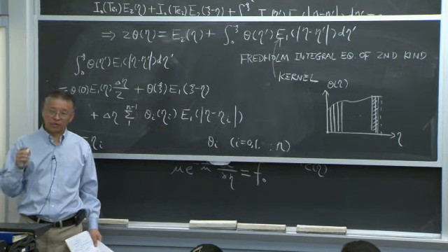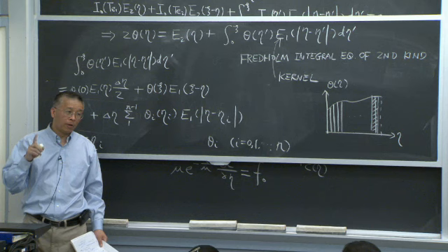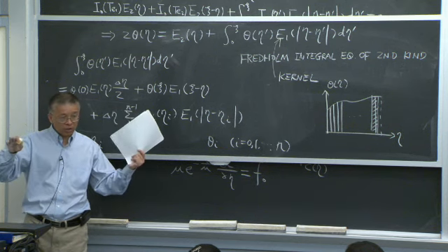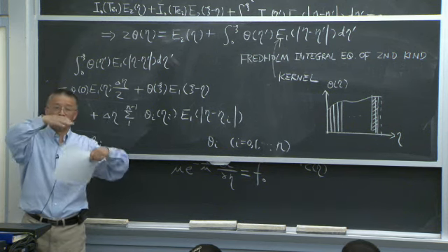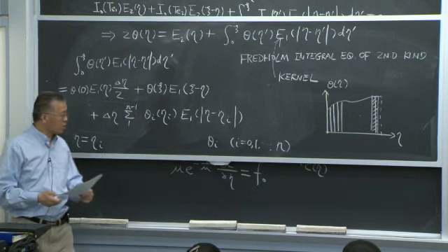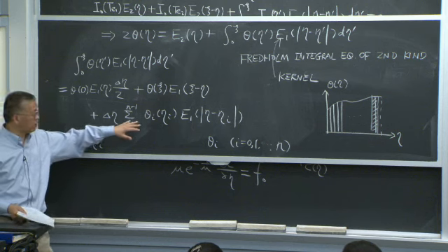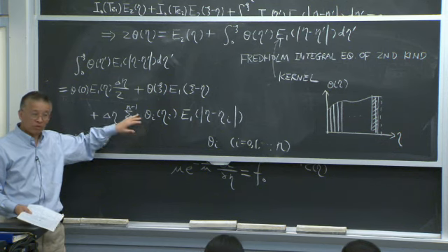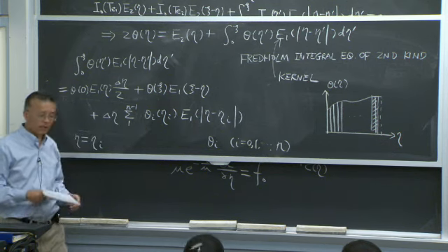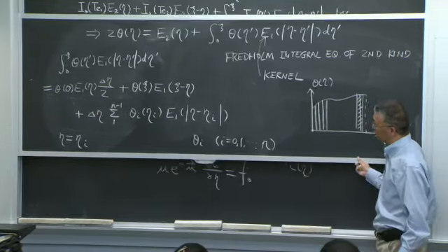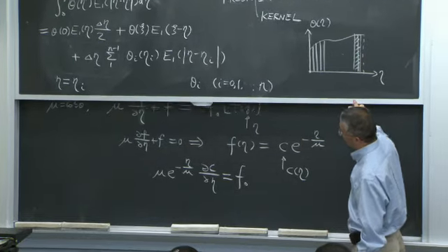And this matrix is different from when you solve the Fourier heat conduction equation or the Navier-Stokes equation. In that case, your matrix is mostly 0, except the diagonal and the two lines adjacent to the diagonal. This matrix is typically a full matrix because every term is non-zero. Okay, so you need to invert that matrix to find the temperature distribution, or in this case the incident intensity distribution.